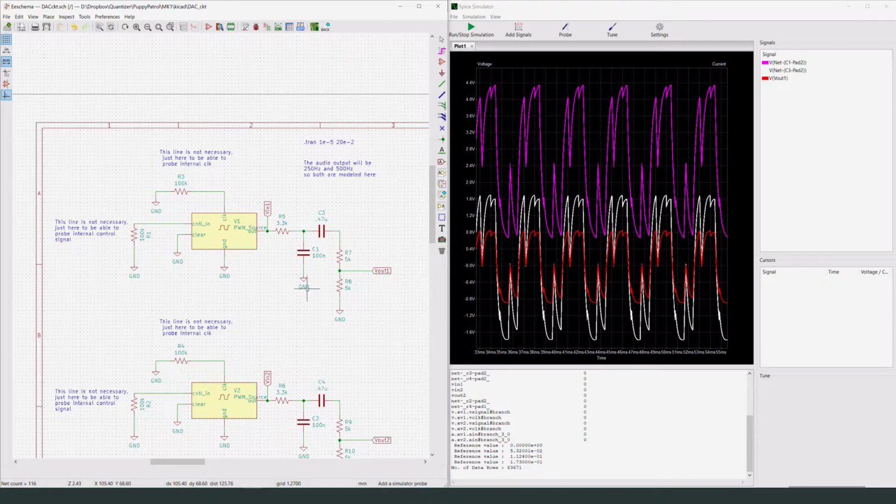And so that's nice. But again, when we built this circuit, we use this to circle around 0. We just select volume. This creates a high pass filter, which is the opposite of this. And so we have a similar problem, but not as bad, where we said, okay, we just want to make sure all the higher frequency stuff gets through, because we want to block the DC value, which is a low frequency, actually at 0 hertz is DC.